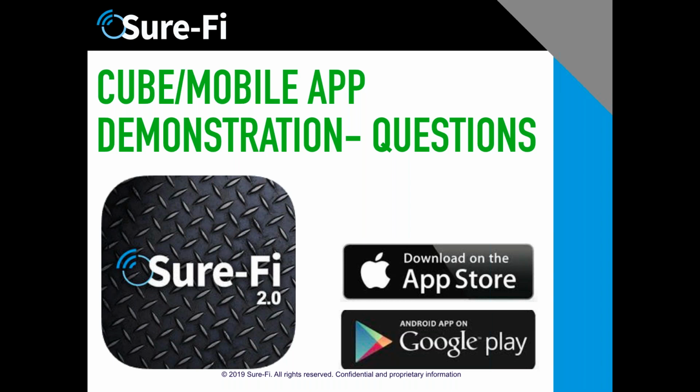We are on 900 megahertz, but we use what's called chirp spread spectrum and chirp modulation. It's kind of like sonar for whales and dolphins. They used this early in the 40s, but they didn't have the processing power until just recently to make this work. Surefire has used this chirp modulation protocol on 900 megahertz to allow us to have our own signal, not relying on Wi-Fi, not relying on anything else, to send your signal throughout these buildings.